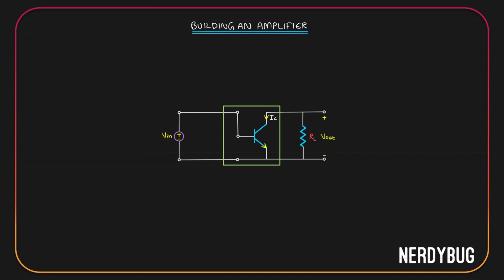So the actual relationship between the collector current and the input voltage will be like this. IC is Is e raised to V in by Vt. One problem we have here is IC and input voltage are exponentially related in this equation. But when we made the idea of an amplifier, we said the current should be proportional to the input voltage. We did an approximation on this. We saw that if the input signal is small enough, the equation can be written like this.